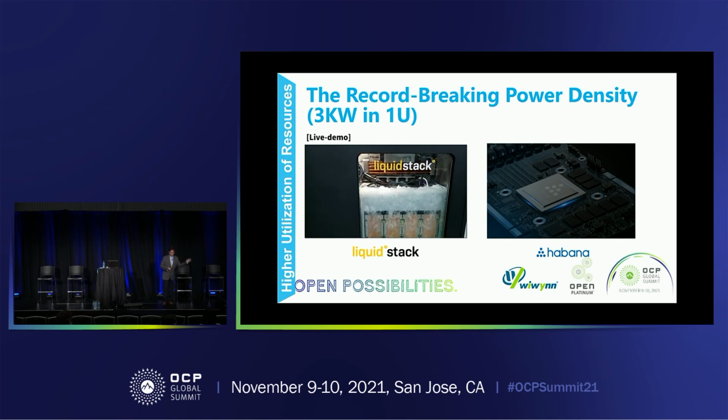And this one is really phenomenal. You should go take a look at this. And we're basically able to cool up to 6 kilowatts in this tank. The coolness about, literally the coolness about the two-phase immersion cooling is that we would be able to cool up to 4,000 watts in 1U. And with the PUE of 1.01 or 1.02, compared to all of the technologies that are present today, this is the best.